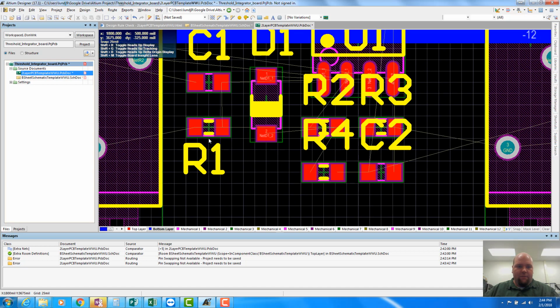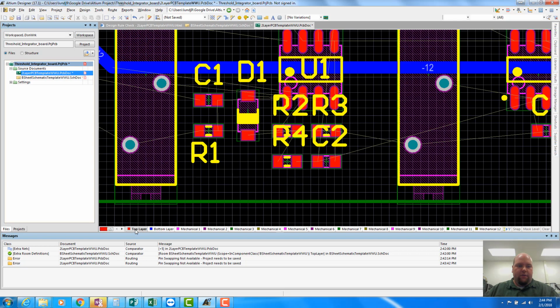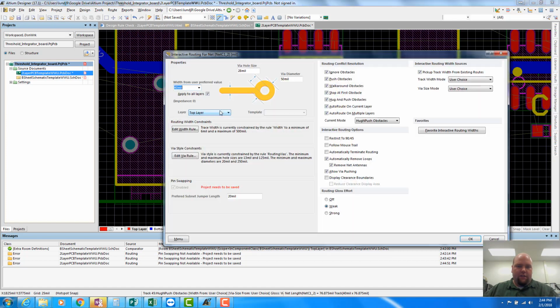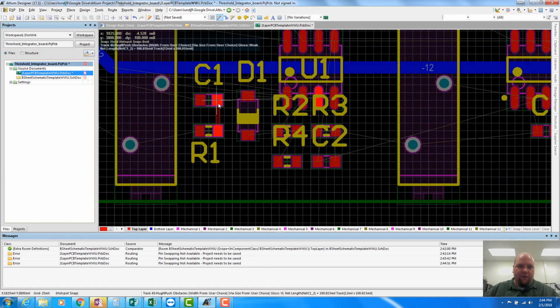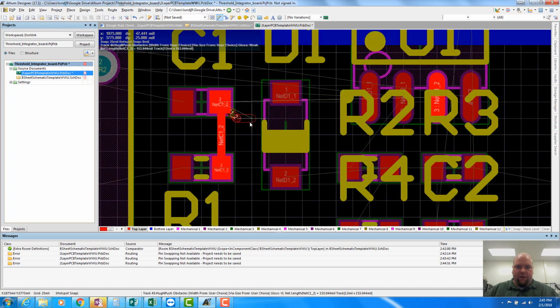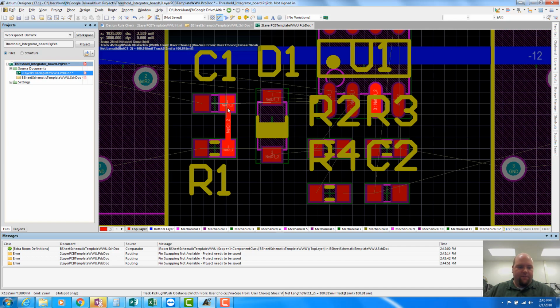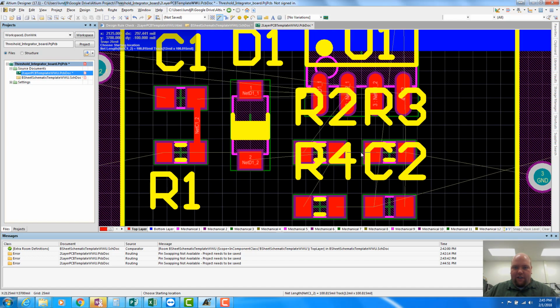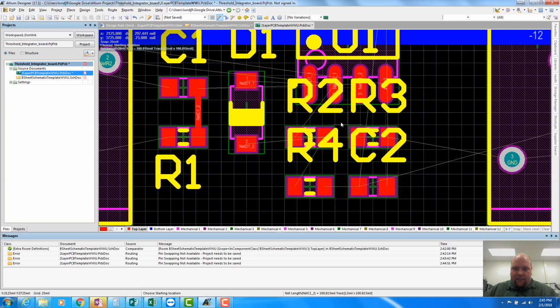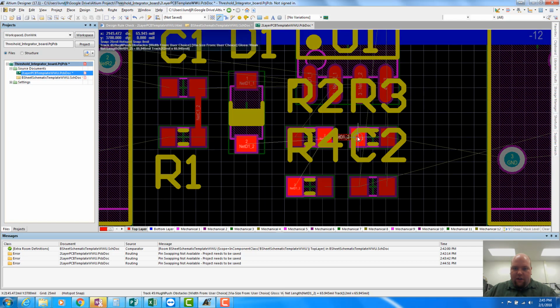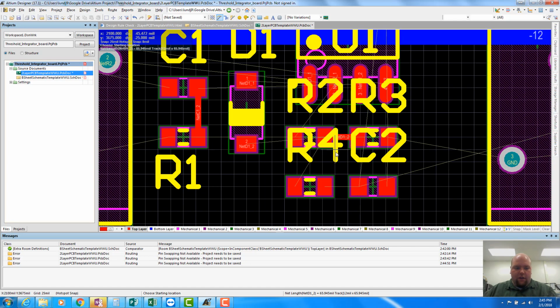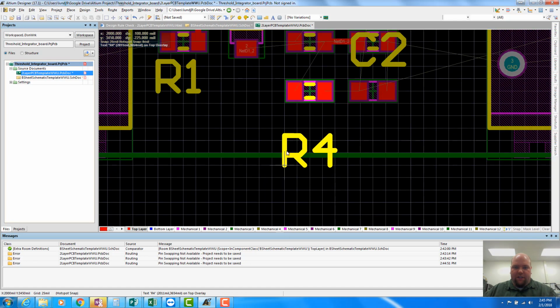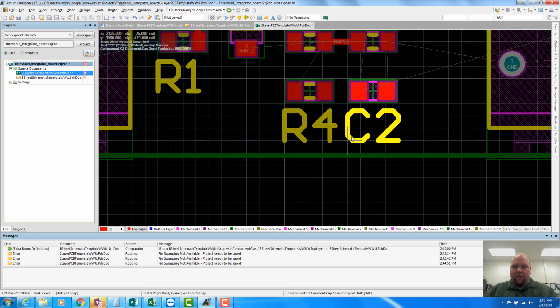Let's start doing some small ball routing here, though. So let's start doing some top layer routing. It's a little bit too big for signals. We'll just do a 12, which I find to be a reasonable signal value. Sometimes I start with these little connections. I just start with the little guys that are close. And this is a part where I want to move these annotations out of the way. Move these names out of here.